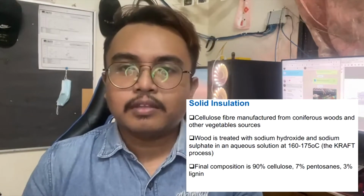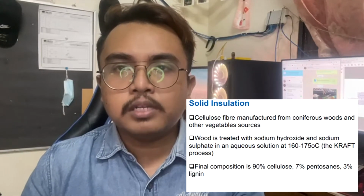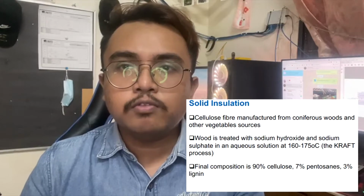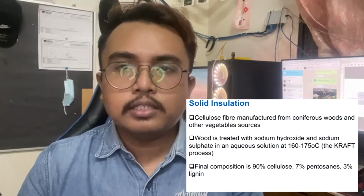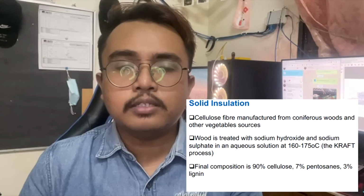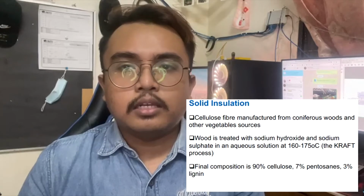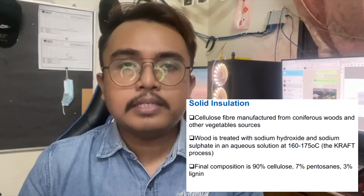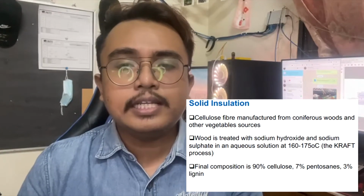Next, I will explain about the solid insulation. Cellulose fiber is manufactured from coniferous woods and other vegetable sources. Wood is treated with sodium hydroxide and sodium sulfate in aqueous solution at 160 to 175 degrees Celsius. The final composition is 90% cellulose, 7% pentosan cellulose, and 3% lignin.